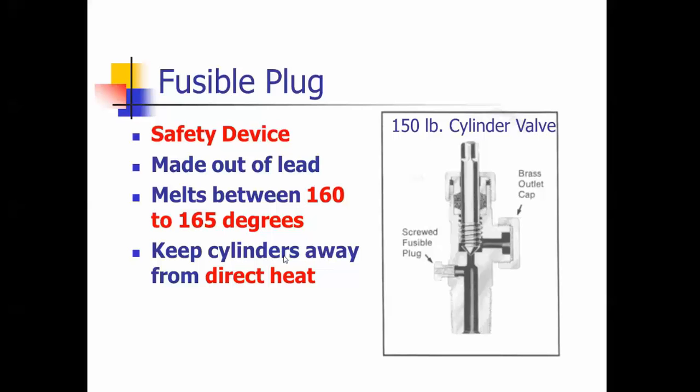And so you always want to keep the cylinders away from direct heat. You don't want to store them outside in the summer where they have direct sunlight on them. On hot days, that plug could melt and you could have a leak, the chlorine being released off of the cylinder.